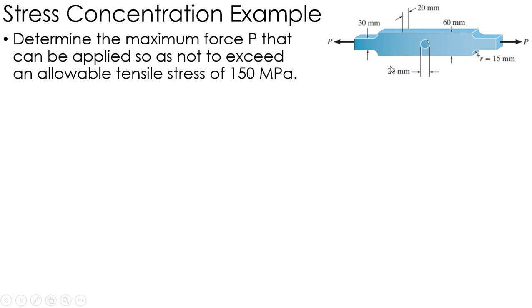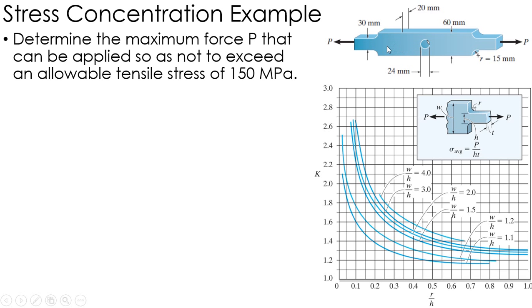So here I've got a bar. I'm trying to figure out what force so that I don't go past 150 megapascals in tension. Again, recognizing that I've got a couple of different stress concentrations, one at a fillet and one at a hole on the inside. Okay, so we'll start with the fillet.